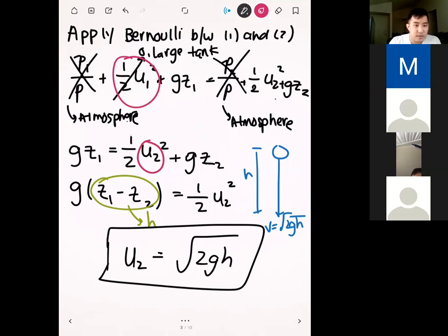Yes. I was just trying to see the relationship, how you mentioned last time that you had your potential, you had your kinetic, and the other term is just pressure now. What would that be considered in terms of energy? Pressure definitely doesn't have a term like kinetic or potential energy, but you can think of it as work. The most common place that you see pressure doing work on a flow is in internal flow. You have pipe flow going from a reservoir to your faucet. In order for it to get there, the pressure has to do work on the flow to get it over that distance.